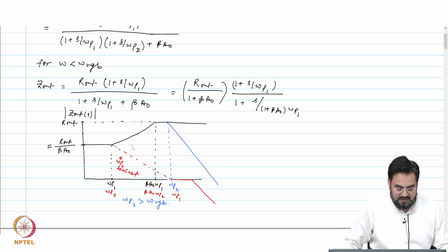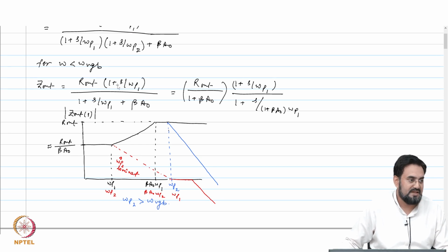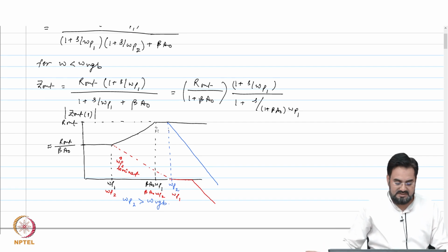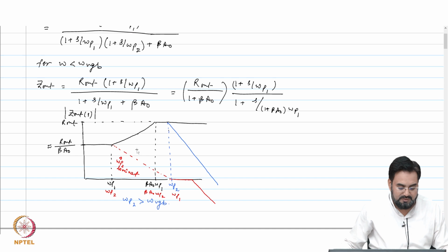And if you look at the high frequency component of this, we have a zero corresponding to the dominant pole if it is appearing at the output of your error amplifier or first stage, and that will degrade your output impedance at higher frequencies and make it worse around UGB. Which means my load transient will degrade due to this zero.